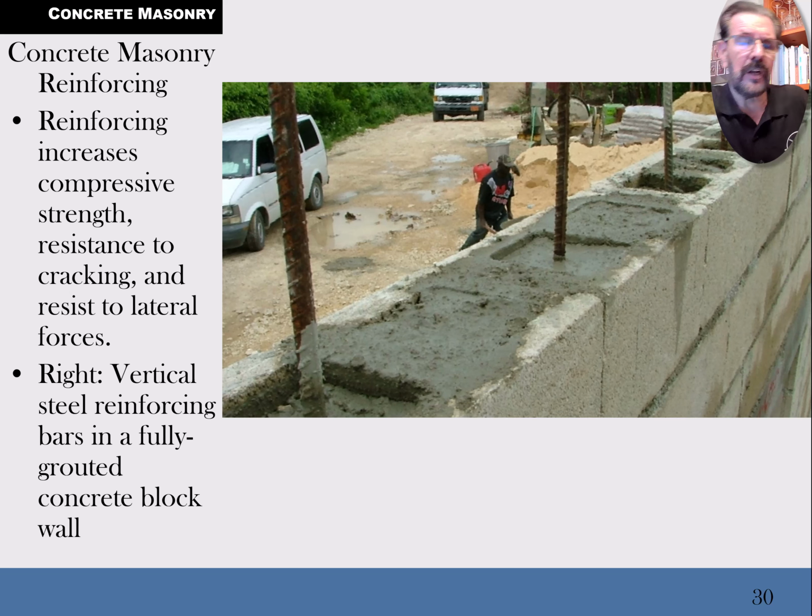You don't make a structural wall by just having a bunch of blocks and mortar. You've got to have the concrete and rebar columns hidden inside them. So these cells are filled, maybe not every single one, maybe every other one or something, filled with concrete and rebar. So you have rebar coming out of the foundation, then you splice some more rebar on all the way up inside here, and then you fill these cells all the way up with concrete. And that gives you these hidden concrete columns bonded to the walls, hidden inside these walls.